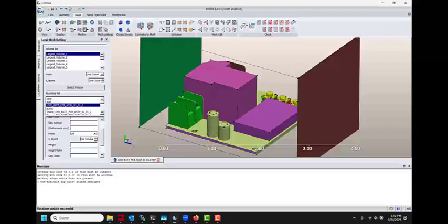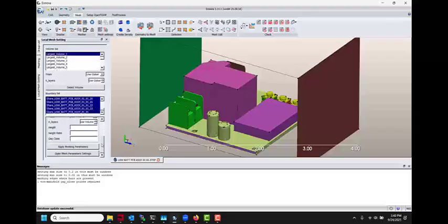And so I can turn on the prisms by saying use volume and clicking OK. I can also now step through the rest of them here. All these need to have their prism layers on. I can pick up all of them at once and go apply parameters.